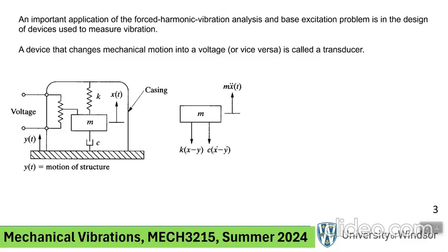What I'm showing you on the left side is a very old-fashioned rudimentary accelerometer. Okay. Now notice that it is a casing, which is mounted on a base, and inside of that casing there is a mass, spring, and a damper. And because you're dealing with electrical reading, there is a voltage source. For example, we can think about this thing as a battery, hypothetical battery, okay?